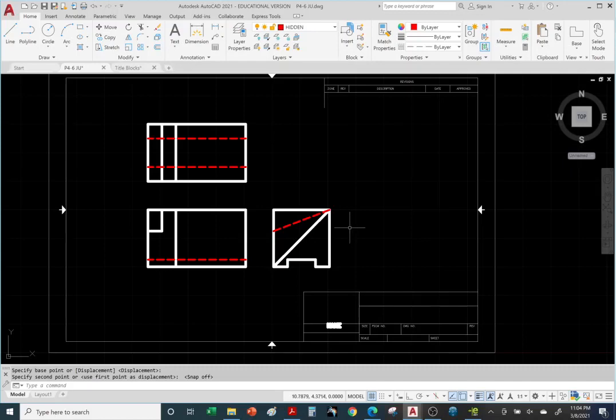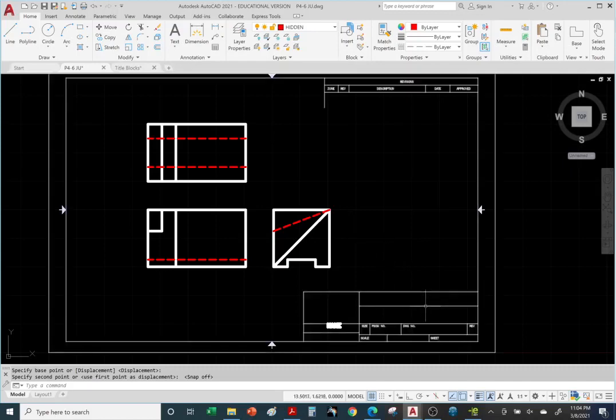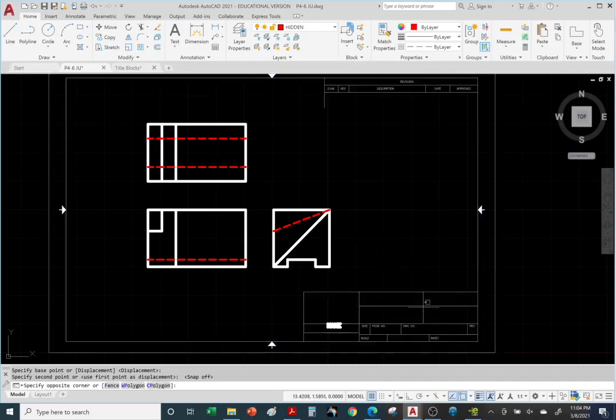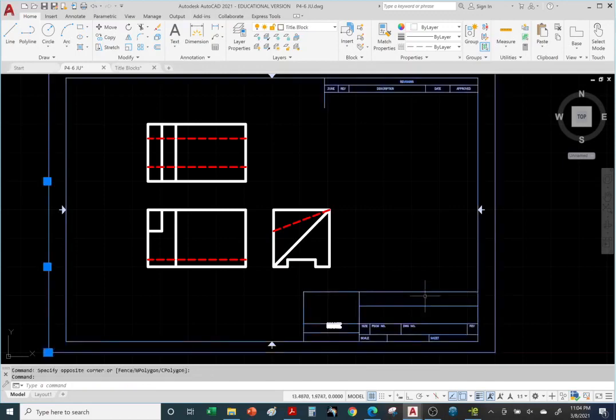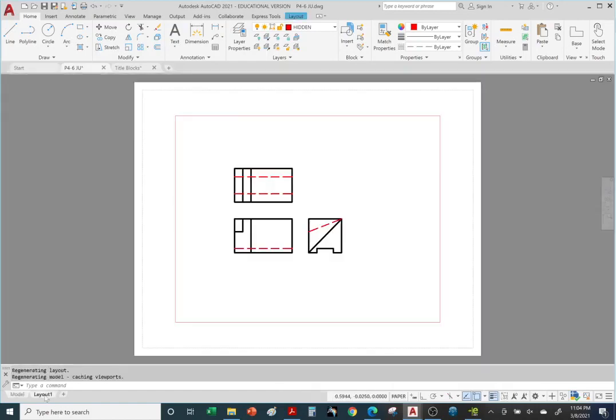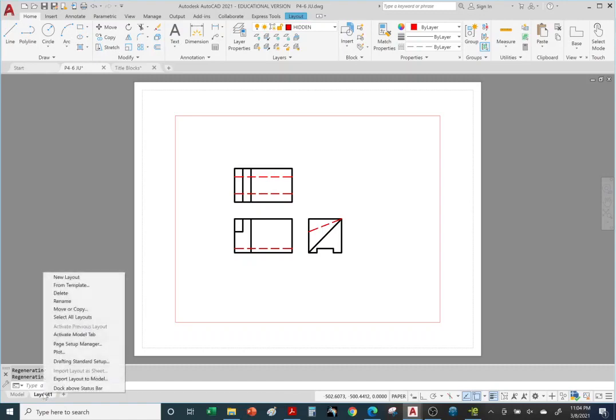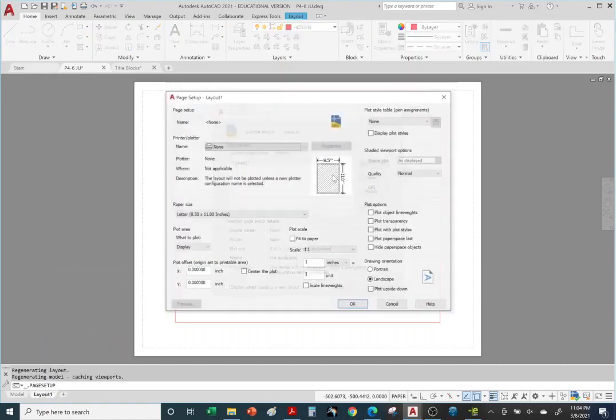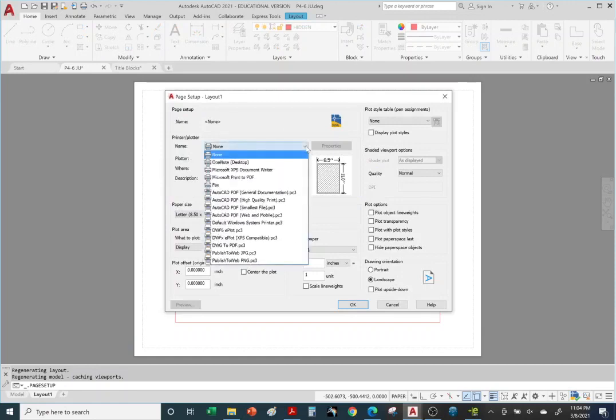All right, so if you choose to put your title block on the layout, let's go ahead and delete this one. And I'll delete the text. So I'll put the text on the actual sheet. Okay, so let's go to layout. It defaults to an A size, 8.5 by 11. I'm going to right click on the layout. Page setup manager. Modify it. You guys should be experts now in how to insert a title block. Go to the drop down.